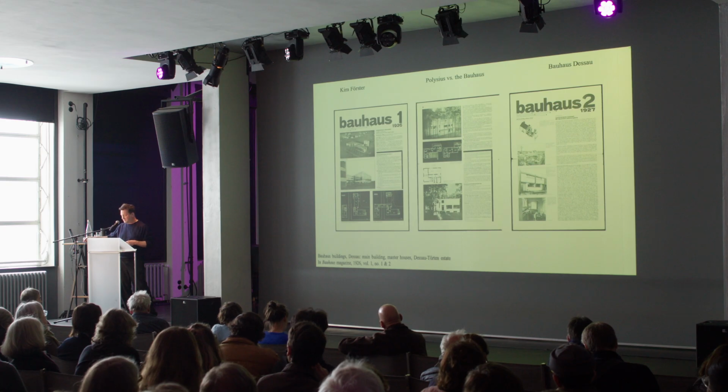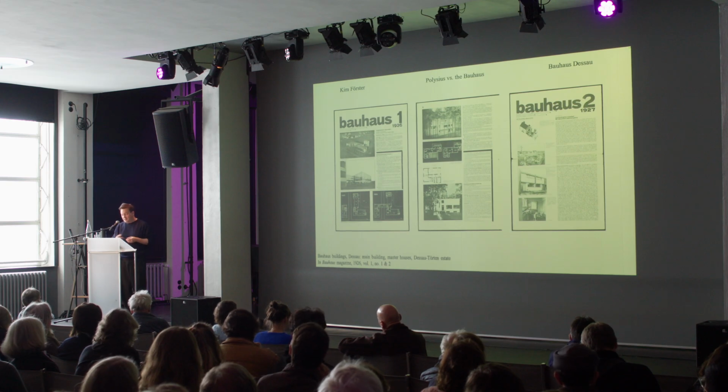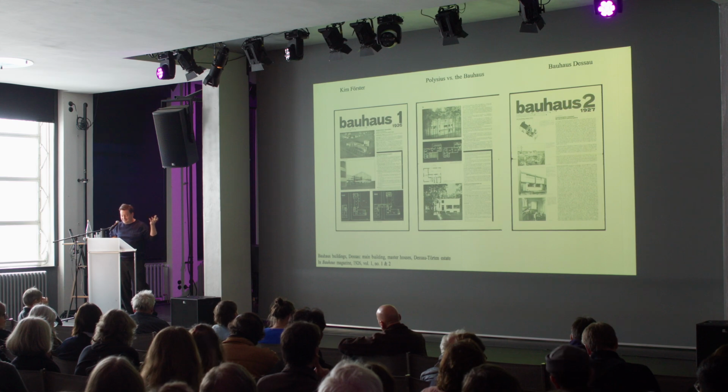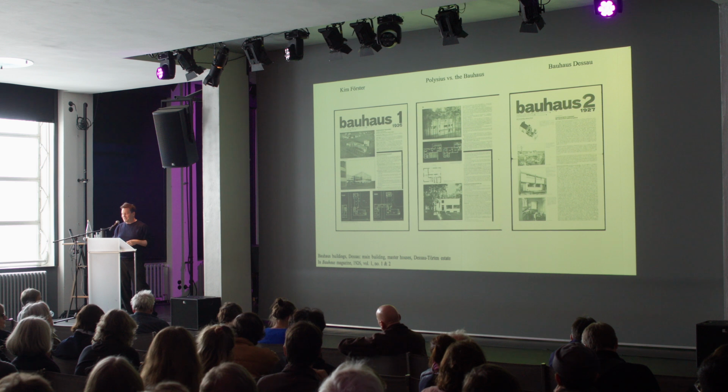And for the master houses in Dessau and Ziebigk, Gropius employed innovative planning and construction using reinforced concrete columns on foundations of tamped concrete, while walls were largely built from what we saw on the poster, Jucker stones, or no, the poster doesn't show Jucker stones, but it's this industrial waste product, slag, with cement as a binding agent, which needs to be mentioned. While he had experimented with this in Haus Auerbach and Haus am Horn previously.